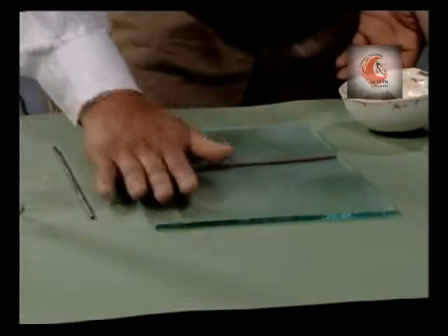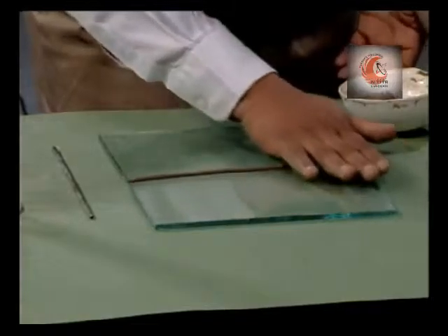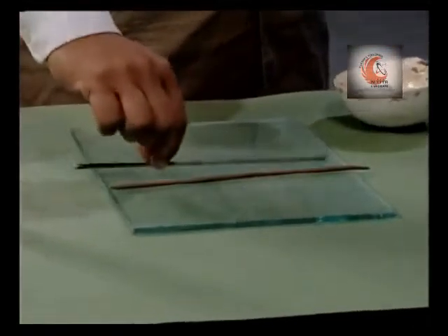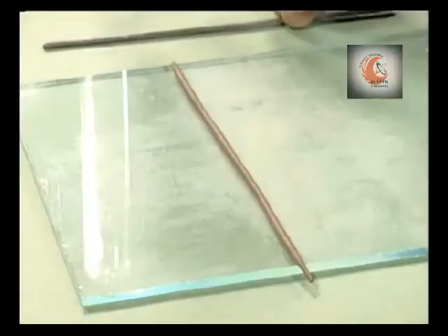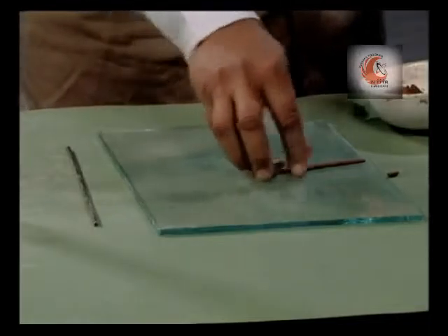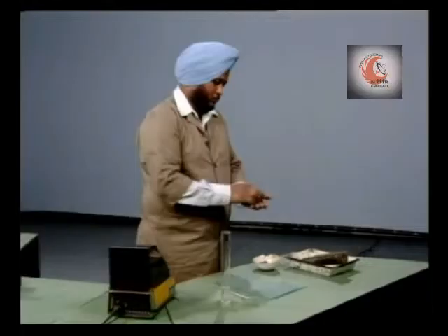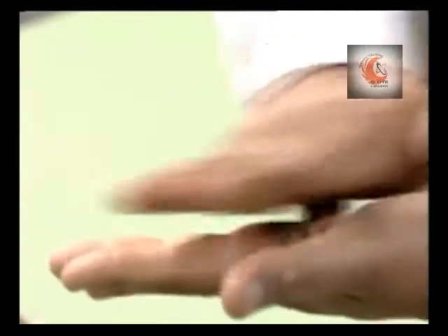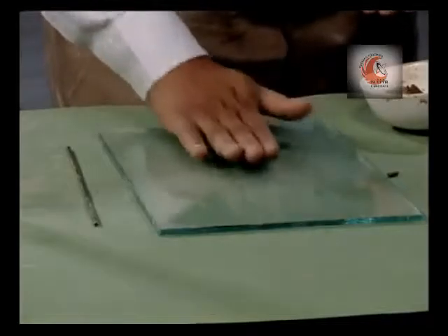Continue rolling till the thread reaches a diameter of 3 mm by taking reference of the metallic rod. Knead the soil of this thread into a ball and roll it again into a thread.